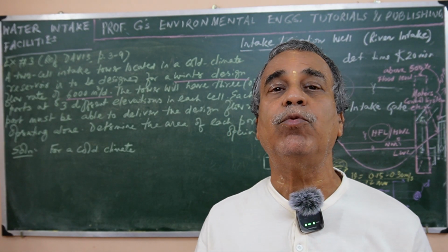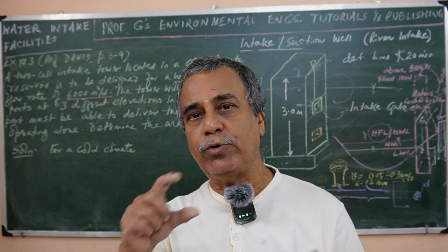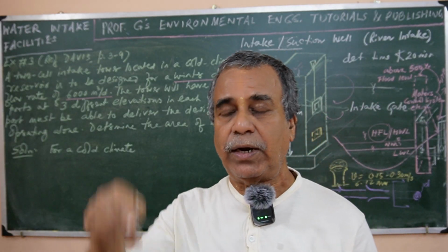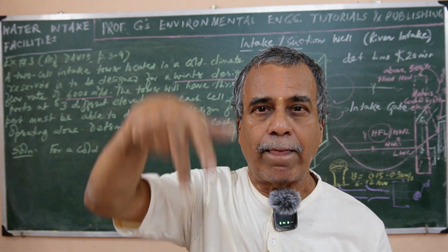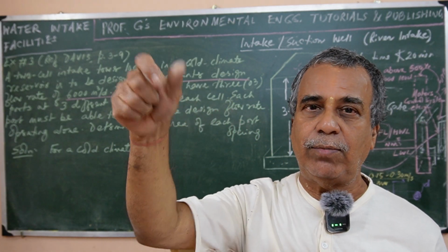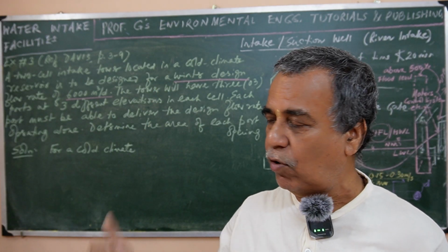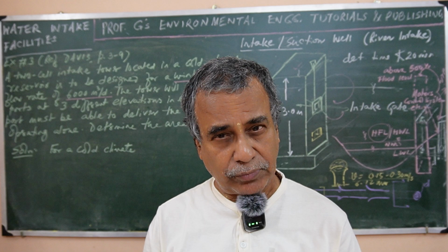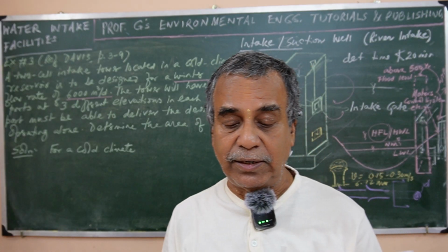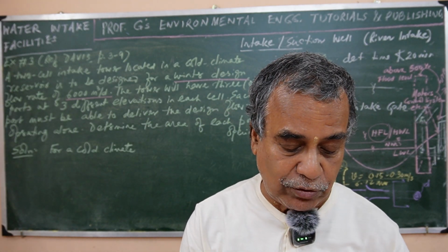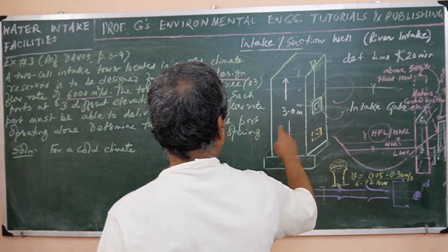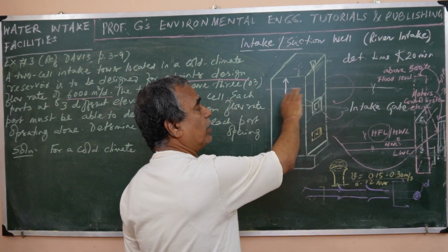Suppose there is turbulence. In that case you have to open the port at the time and level where turbulence is minimum. There is a sluice valve, also operated by a gate valve, which I have already explained, so I don't need to explain it further. Then there are stratification and lake turnover, which we also have to consider, so that flexibility can be exercised.